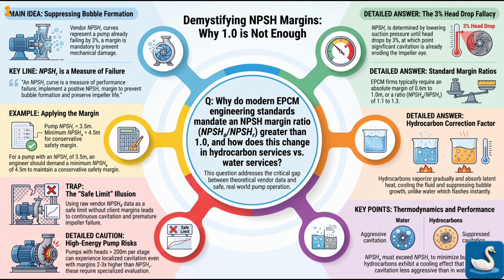The foundation of this mandate lies in correcting a widespread industry misconception known as the 3% head drop fallacy. The standard NPSH required curve, or NPSHR, provided by a pump vendor, is not a safe operating baseline. It represents a mathematical state where the pump is already undergoing a 3% developed head drop due to cavitation. Therefore, an absolute positive NPSH available margin is required to suppress bubble formation and prevent mechanical damage before it even begins.